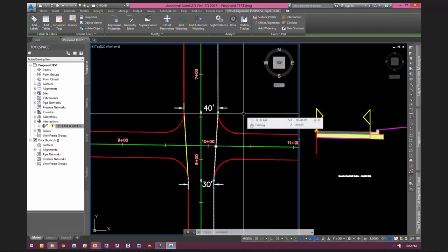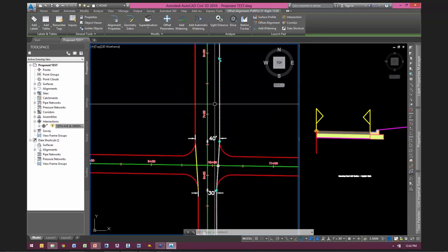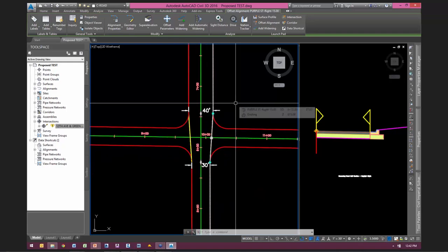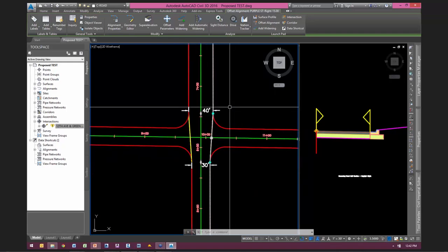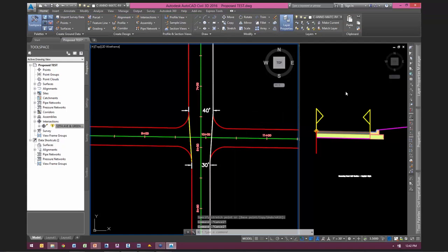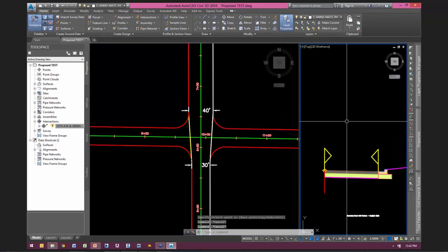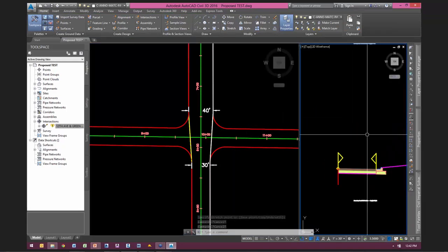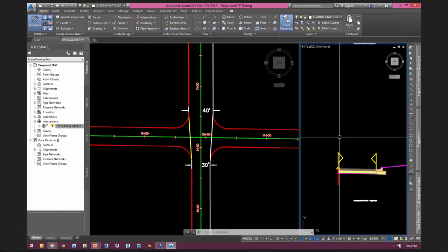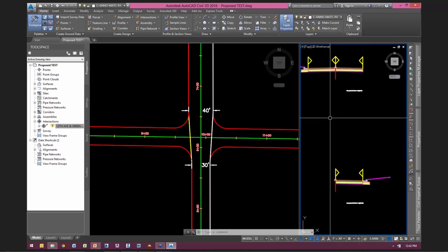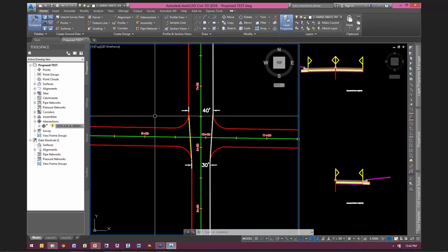Secondly, we need profiles. The corridor tool will not build profiles for us. But what do these profiles need to look like? Well, right out here, they need to be just 2% down from center line. So I'm going to employ a different strategy here. I taught it in some other classes recently. It's the use of auxiliary corridors. And I taught this in another webinar too, so I'm going to go through this quickly and not explain it in detail. Again, you can go check out another webinar. But what we're going to use is a setup corridor.